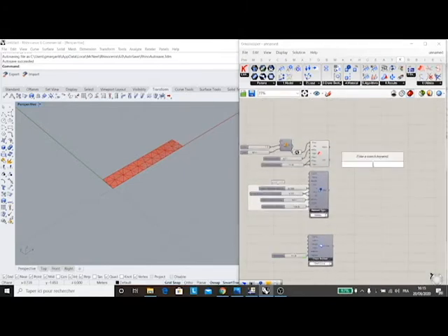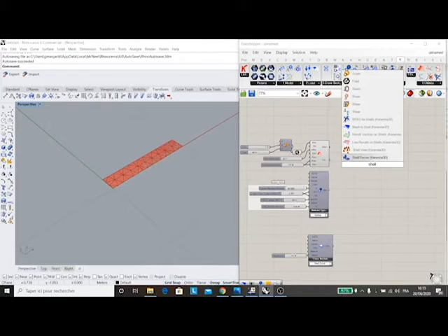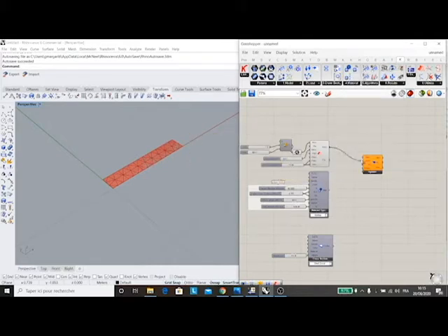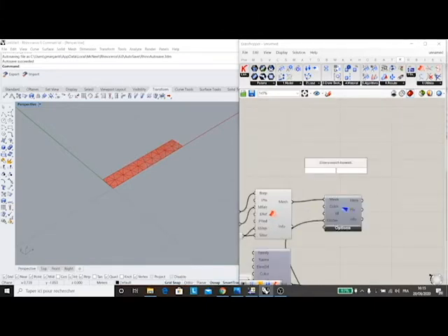And now I can make my finite elements that are going to be used for the structural calculation. I assign cross-section, I assign material to cross-section, and I will give it a name. It's many times useful, especially when you have a more complicated setup.